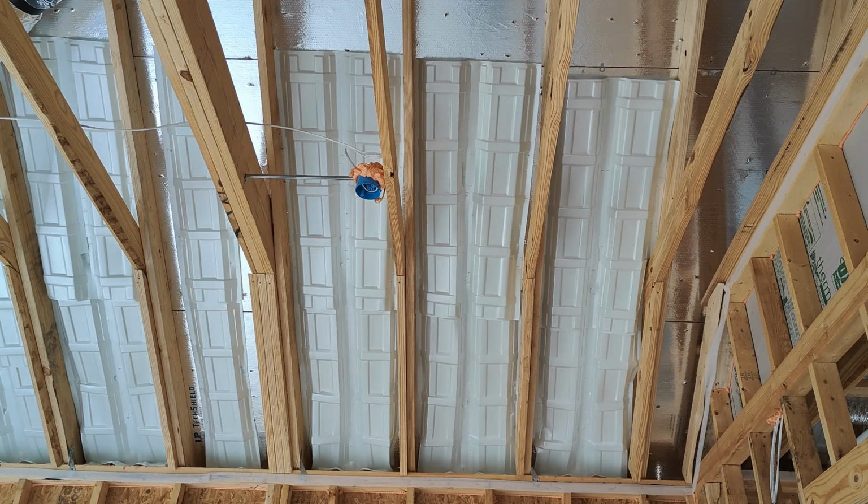Wind washing can either be blowing insulation off the top plate, or, if this is going to be batt insulation in that vault ceiling, wind washing is basically allowing air to move through insulation, which lowers the effective R value, which allows heat to actually hit the cold surface. Doing it this way and fully filling the cavity, making sure it's stapled correctly to the top plate, allows for outside air to enter the attic to replace the exhausting air going through the roof line.